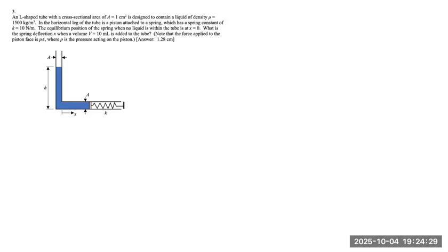If the diameter of the pipe was not small enough, what we would actually have to do would be more complicated, because we would have to take into account the height difference, since pressure is related to the height of the column of water. So we would have to take that into account if the diameter cannot be assumed to be small enough compared to h, the height.